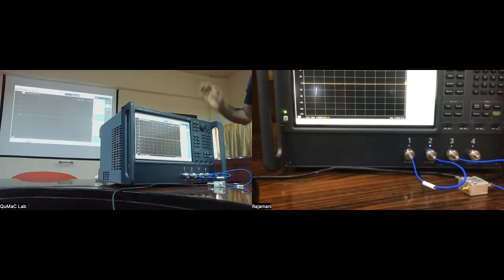All the instrument is doing is that. So first I explained that this phase evolution is a trivial response of the cable. Okay, it's just increasing as a function of frequency because of the time difference it takes for the signal to go from port 2 to 1. Remember, we're measuring S21, right? So the phase when it started versus the phase when it received at the other port, it's going to accumulate an extra phase because of the time difference. And that phase accumulation will be more at higher frequencies. So omega times delta t is basically the phase accumulation, and omega is varying linearly across the x-axis. So you saw this linear thing.